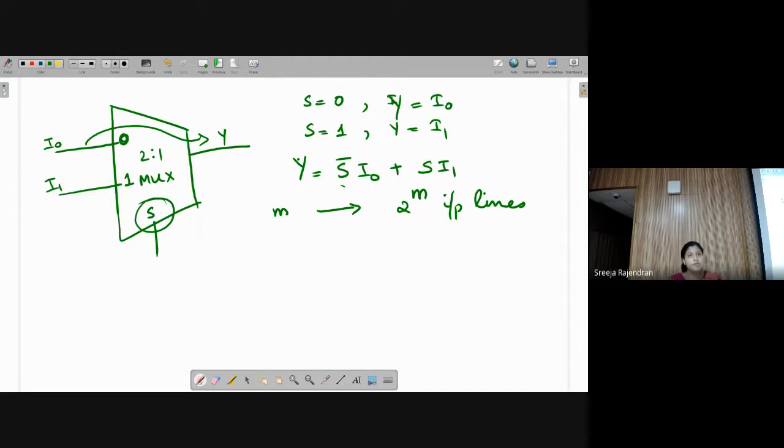So we saw that, instead of using the gate-wise implementation, here I have an AND gate and an OR gate also, so I need two ICs. I was mentioning the number of ICs I require, because AND and OR functionality will not come on a single integrated circuit chip, so we need to go for multiple chips.